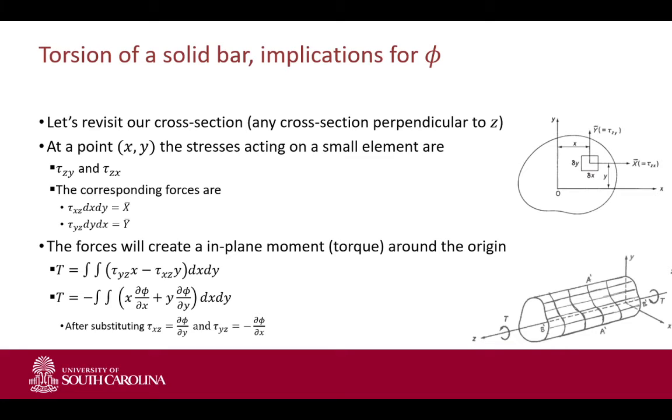So why not go ahead and relate this to a torsion or a moment. We take the integral of every small element on that cross section, and we multiply that by an arm, and we define the direction in our coordinate system. Counterclockwise is positive.